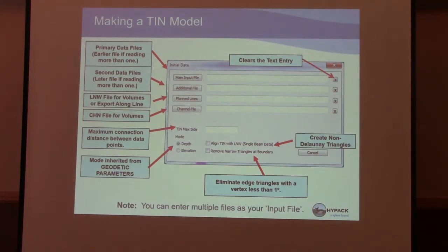The second thing is, unless you're doing a huge data set, and you see when I said we got a 5-foot radius and we realized we didn't connect a lot of points, I can just go back here and set it again and it'll rebuild my grid, rebuild my tin. Huge data sets might take me an hour, but smaller data sets aren't going to take that long.